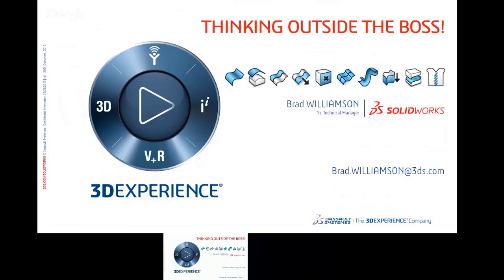The second thing we do in 2018 is, say you've scanned in what should be a planar surface. Well, the mesh body doesn't see that as a plane. It sees it as a bunch of tessellated features. 2018 has a little painter option that you can now just paint over a series of those faces, and it will interpolate that and turn it into a planar or any kind of analytic geometry, cylindrical, cone, toroid, and so on. So there's some better tools in 18. Try that out, if you're needing to solve those kinds of problems.